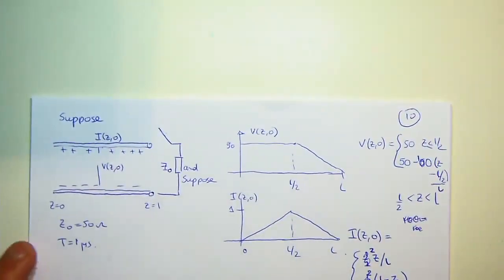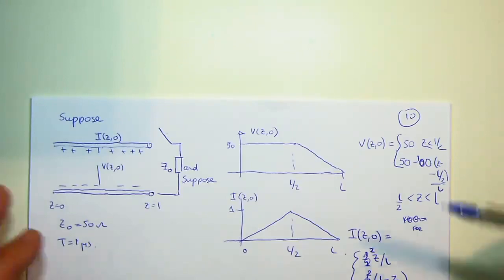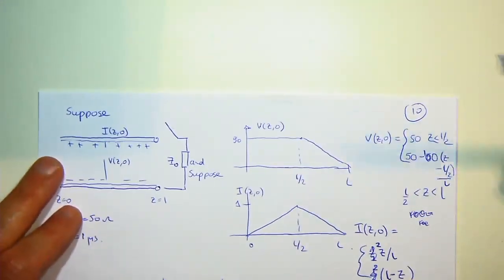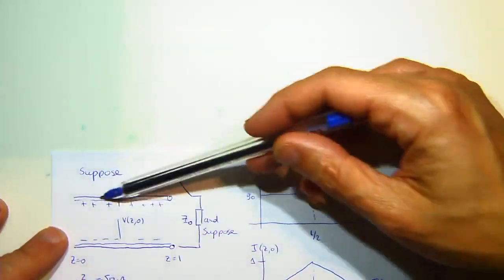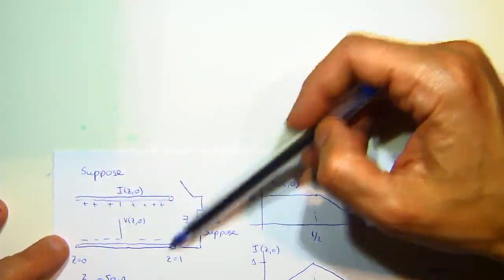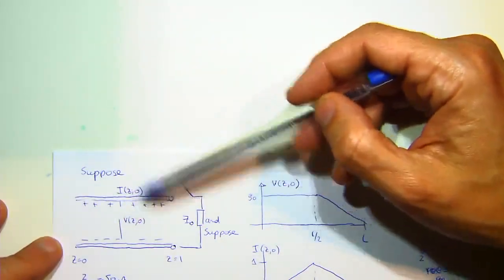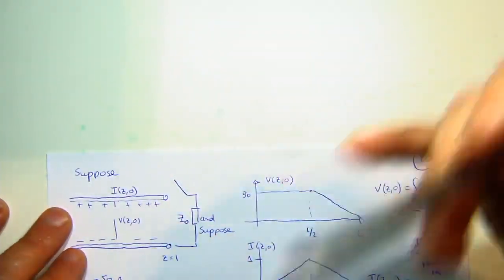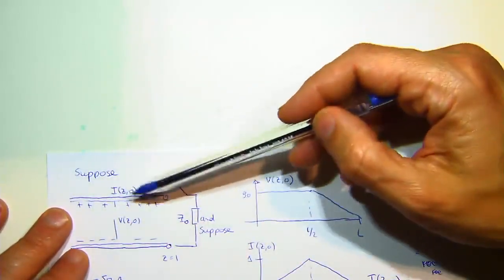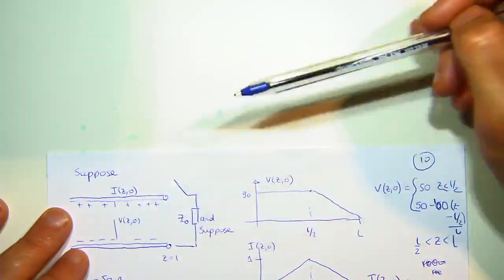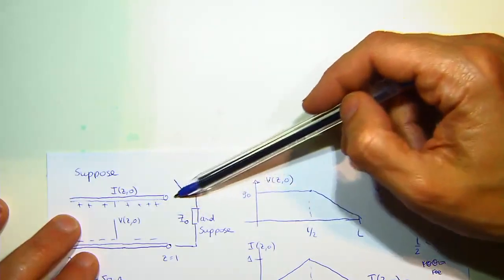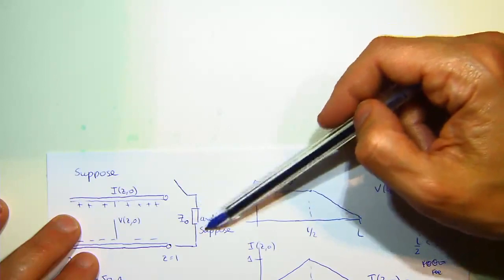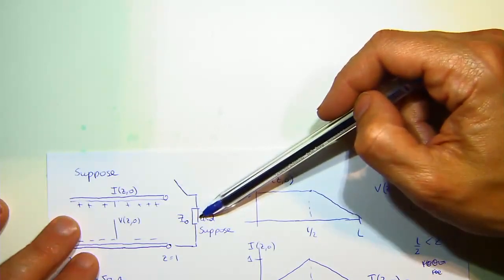you should care, because what we're going to do now is assume, for argument's sake, the following system. We've got a transmission line which is unterminated on both ends. It's got a characteristic impedance, but we had charged it at some time in the infinite past, and it's got a voltage and current standing wave pattern on it. At some stage in the future, I'm going to close this switch, and I want to work out what the voltage and current is going to be across this load.